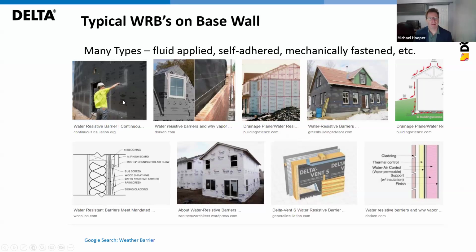And the whole idea behind these is to improve building performance and durability. This is what's going to limit air infiltration and exfiltration. It's going to conserve energy. It's going to resist water infiltration while oftentimes allowing water vapor to escape the building and dry out and maintain that building durability. So it's key that we incorporate these aspects into the assembly, but whenever you introduce components, you introduce complexity. With that complexity comes the risk of things like fire propagation.